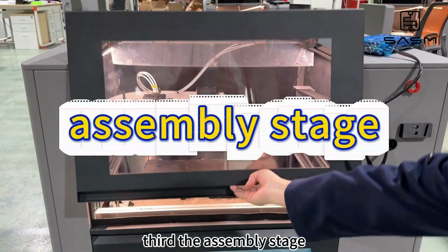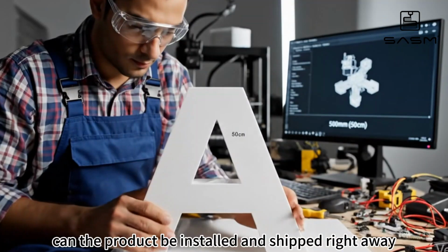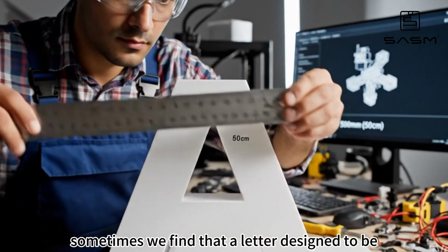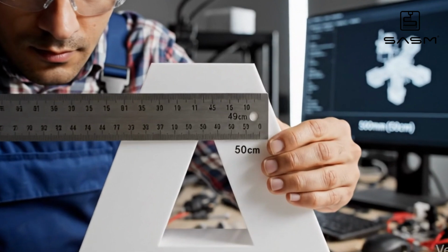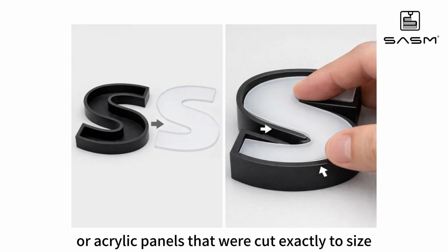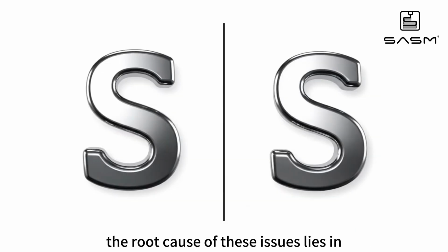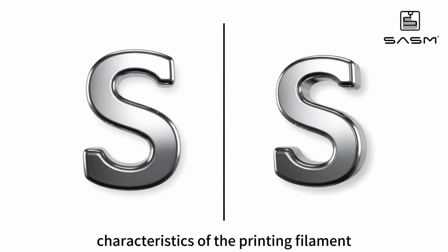Third, the assembly stage. After printing is finished, can the product be installed and shipped right away? Not necessarily. Sometimes we find that a letter designed to be 50 centimeters ends up being 49.5 centimeters after printing. Or acrylic panels that were cut exactly to size simply cannot be installed. The root cause of these issues lies in the thermal shrinkage characteristics of the printing filament.